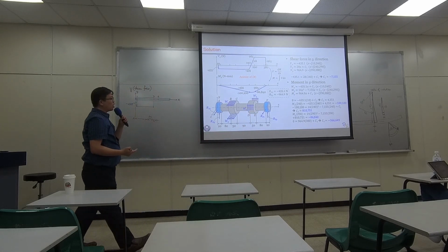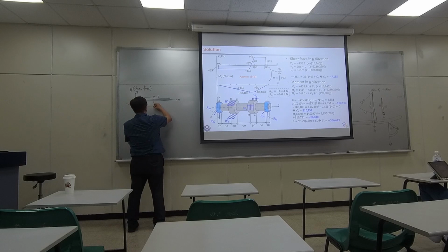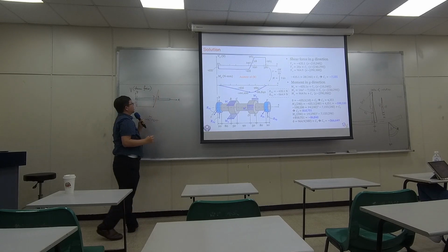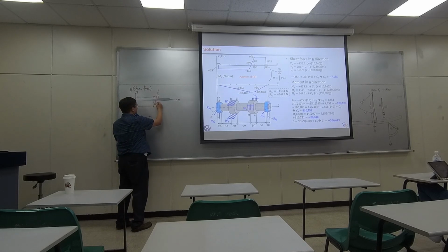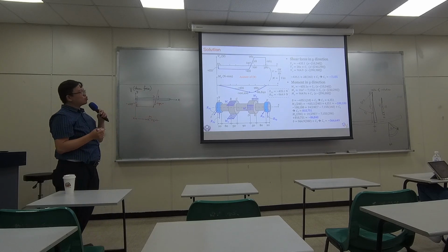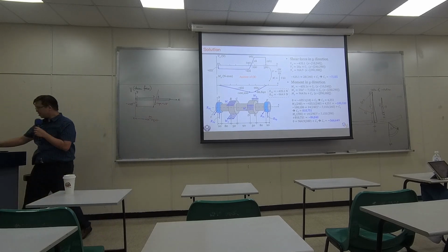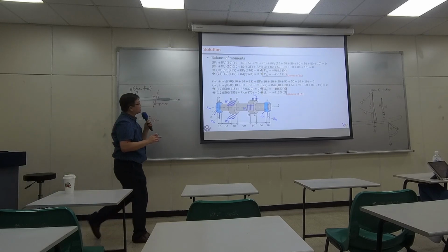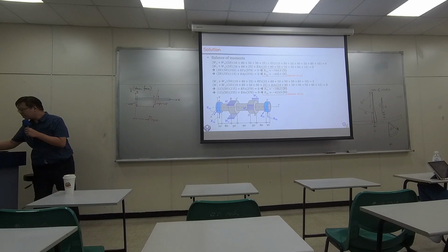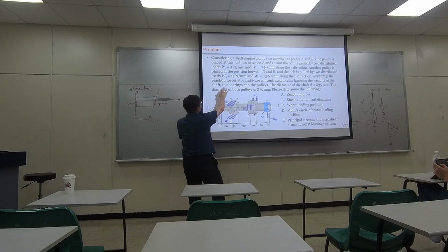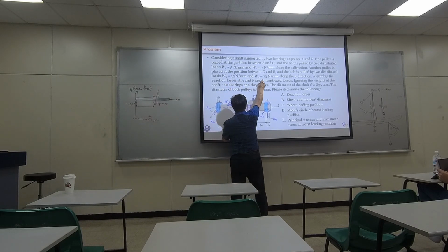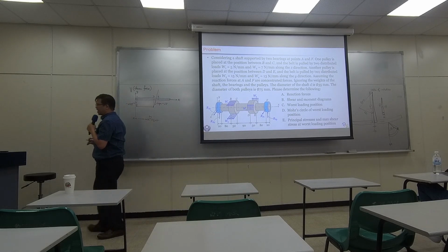For the distributed loads, you will be increasing whenever you walk toward right. And there's a slope. The slope will be equal to how much distributed load you have, which is 28. Why? Because W3 plus W4, 15 and 13, sum them up is 28. Okay?